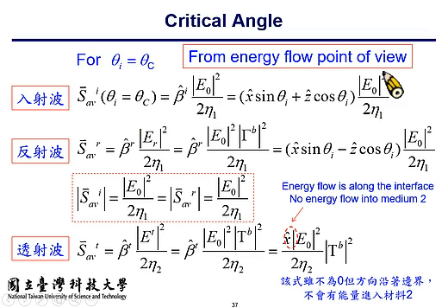As you can see, the magnitude equals E sub 0 squared divided by 2 eta 1. The vector in front tells you the propagation direction. So the second half of the representation tells you the amount of incident wave power density, while the first part,